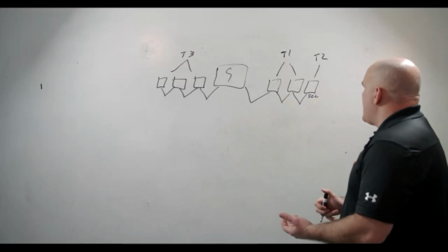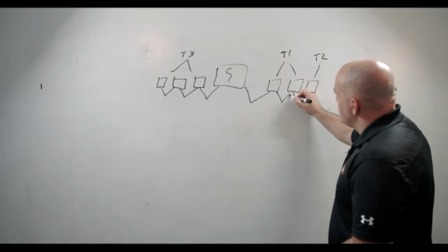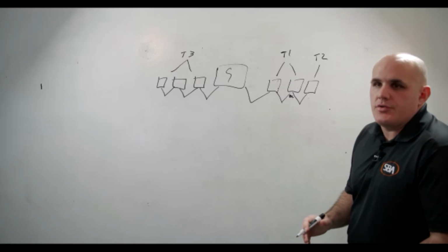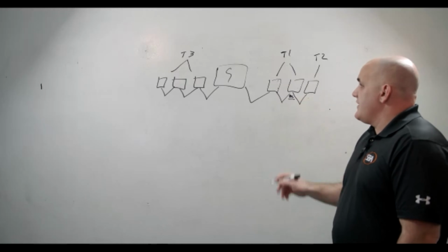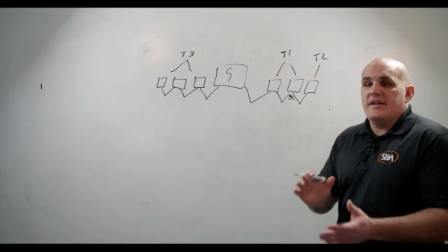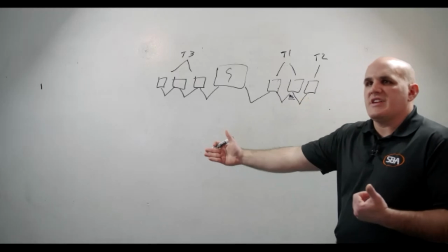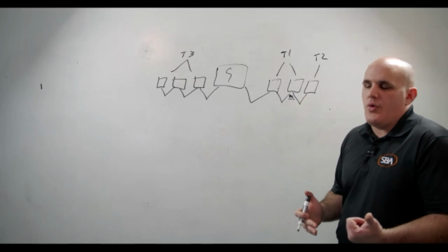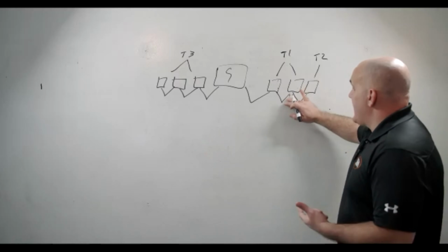The problem is, if I turn the end-of-line on here, then all controllers downstream from that, you're going to lose communication with. So whenever I am looking for end-of-line issues, I look for whether it stops at a certain point and afterwards I can't see the controllers. Then that is either an electrical break in the wiring or an end-of-line issue. So that's how I start to work that out.